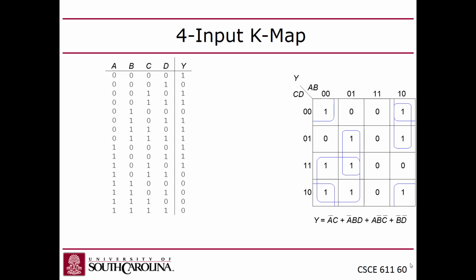In this case, this is my favorite one. It turns out that there's a 1 in all 4 corners, so you can draw a 4-element grouping that hits the corners, because the Karnaugh maps go around the edges. They loop back. So the implicate that corresponds to the 4 corners is going to be what?